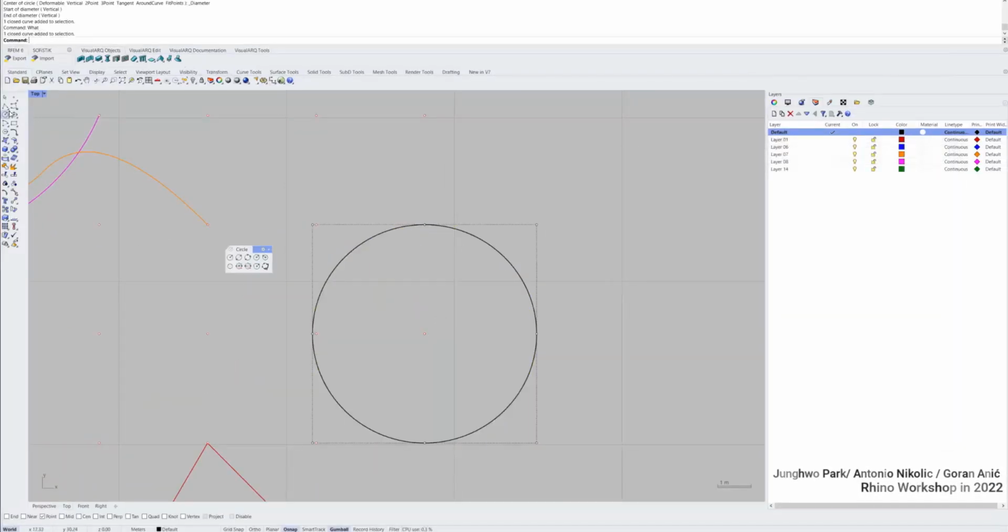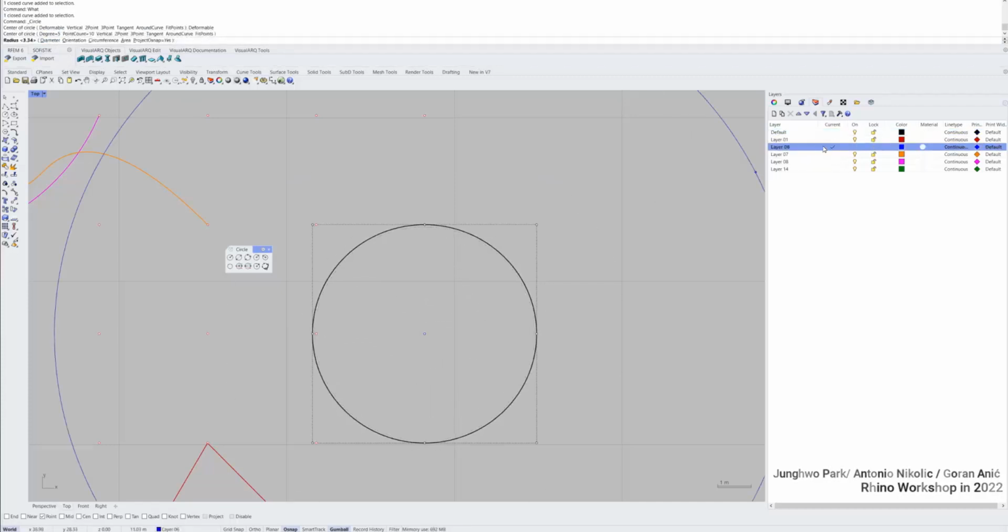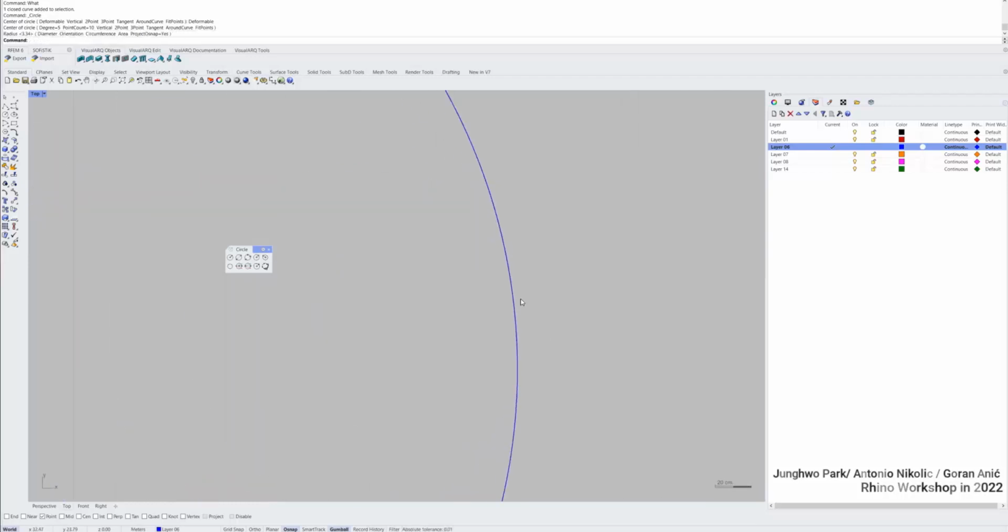But when you click on circle, there is also deformable circle, and you can set the degree. I'm going to draw exactly the same circle with a bounding, which is a degree 3 curve. With your eyes, when I zoom in really close, the deformable circle does not have a consistent radius.